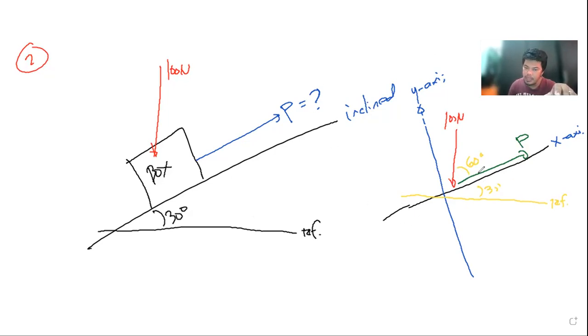So the component P, we have here the force P. That's equivalent to, so try to take a look at this one, 100 cosine of 60 degrees. So that's actually 50 Newton. Now if you cannot imagine how we create this 100 cosine of 60, just have this one.